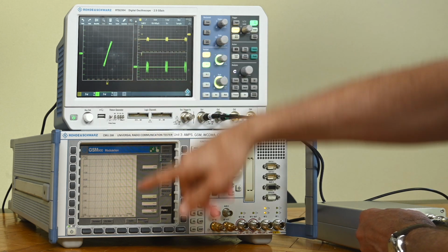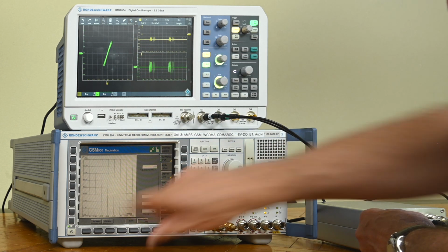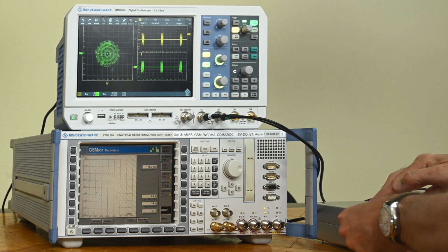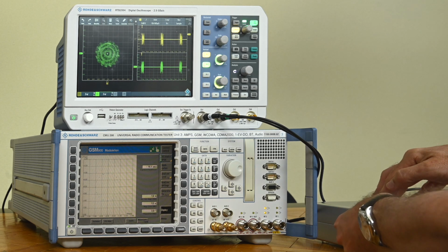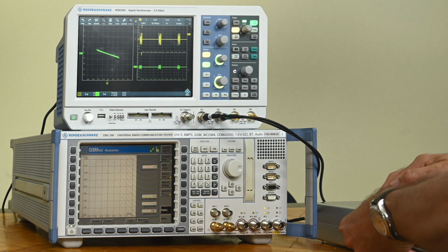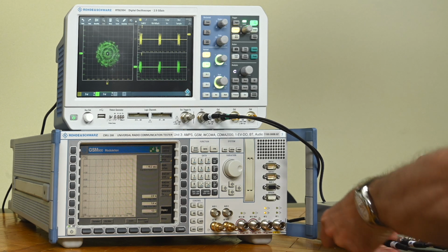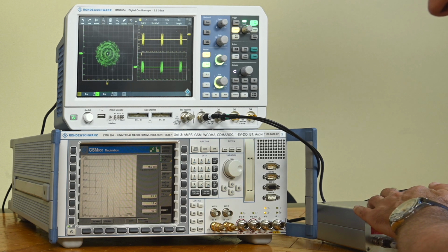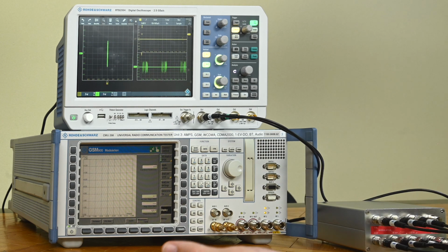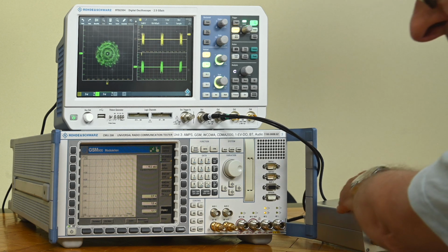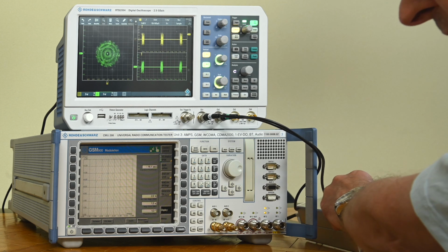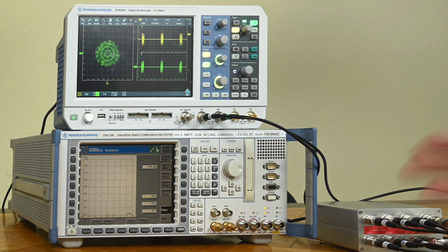We still see something here. This is completely disappearing. I think this is a trigger issue. So I just removed the I in the transmit path. If I remove the Q in the transmit path, it also breaks the chain. If I remove I in the receive path, everything disappears. And if I remove Q in the receive path, everything disappears. And so this is basically telling me that all the IQ signals are properly going in and out.